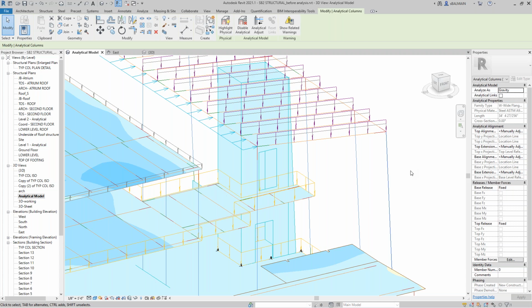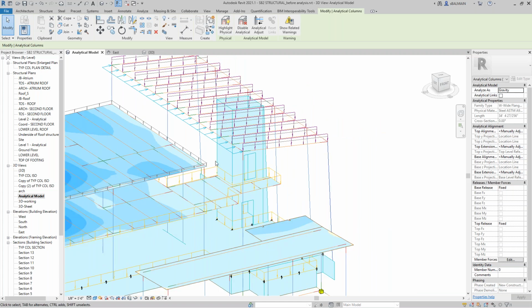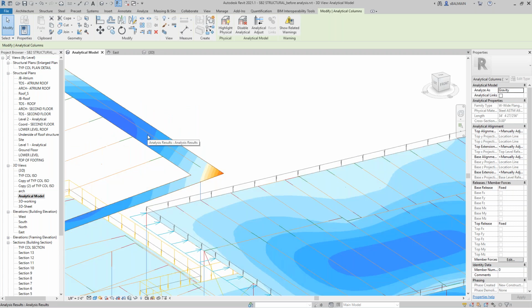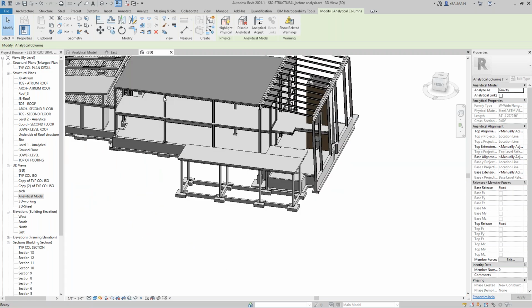It's good in your favor, but sometimes when it's exactly the same, nodes are not connected, you know. So when you go through Revit, it has analytical elements. It means that, for example, let me explain. Here the beam, here it's in this slab. But for real, this beam is at the bottom of the slab.